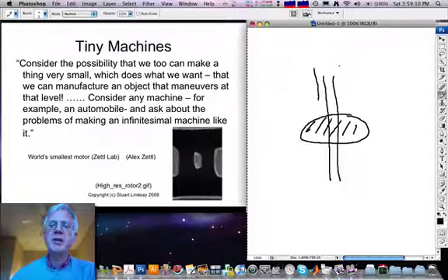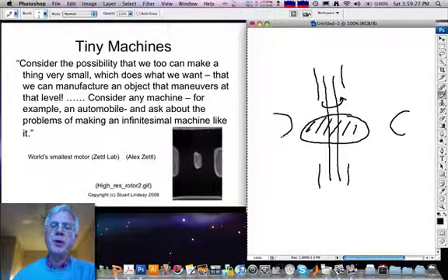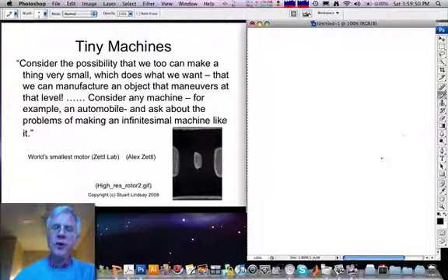And the carbon nanotube itself consists of multiple walls of carbon nanotubes. And because of the very smooth surface of the carbon nanotube, it's free to rotate like an axle on an almost perfect bearing, so that as the electric field is applied between these two pole pieces here, this whole object can rotate. To give you some idea of just how small this device is, the smallest carbon nanotubes at the center of this thing might have a dimension of about 2 nanometers across. This wonderful device was made in the lab of Alex Zettl at the University of California, Berkeley.